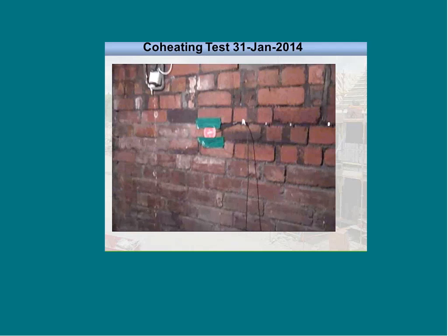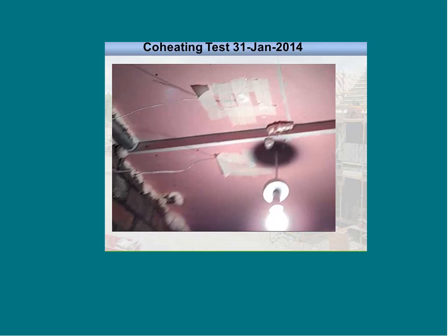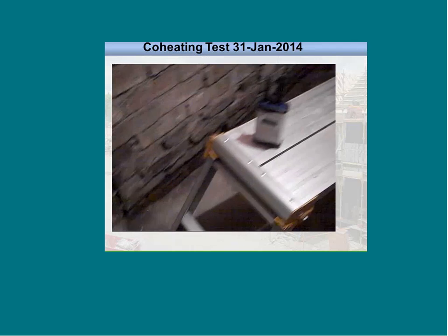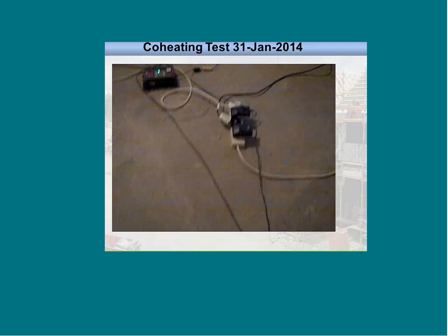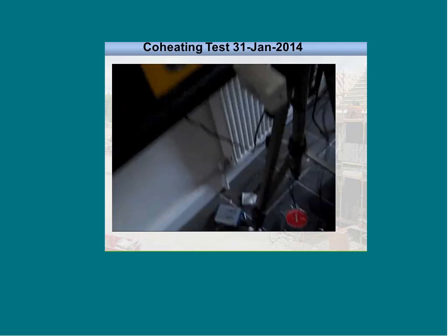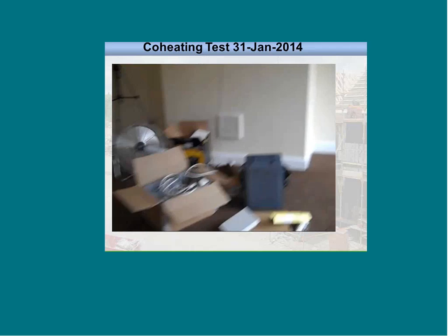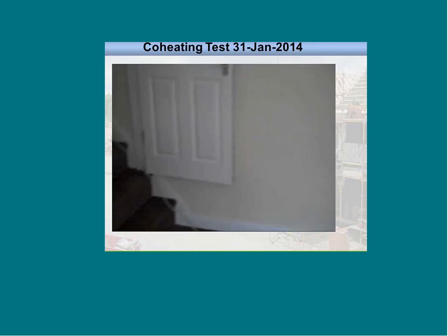The second option is also a simple linear regression. This we obtain when we divide all of the terms in the equation by delta T. This way we obtain the equation on the right on top of the graph. The advantage of this is that we can also visualize the method in a two-dimensional fashion. On top of that, moreover, we can estimate both the heat loss coefficient and also the solar aperture coefficient as a part of the linear regression. You can see on the graph that the heat loss coefficient is seen to be the intercept of the regression line with the y-axis. And the solar aperture coefficient is determined as the downward slope of the same regression line.